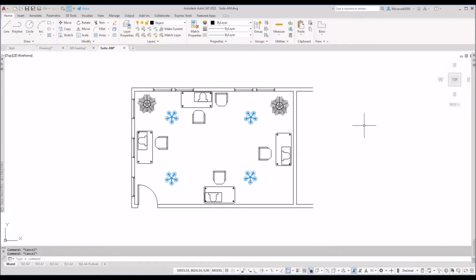Now, another option when you are working in CAD for selecting objects: if I, for example, say move this, what shall I move? These two objects here, this one and this one, and move them from there down to there. I'm moving them down the screen, and hit enter. Also, I'll click to move them. And then I decide, well, I didn't really move those objects far enough, or I want to select all of those objects again. Now, if it was a really difficult selection set that you created, it can be a bit of a pain having to select them all again.